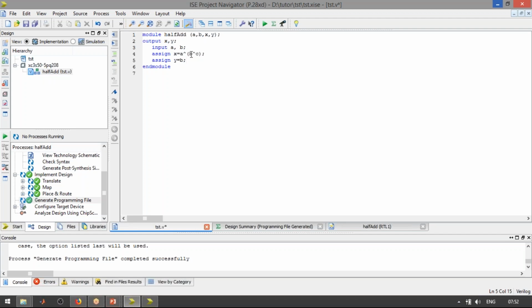But LTSpice is free software, right? Yeah, LTSpice is free software, but it won't support AMS. It doesn't support mixed signals. It only supports the SPICE language. So if you want SPICE modeling, you can prefer LTSpice.